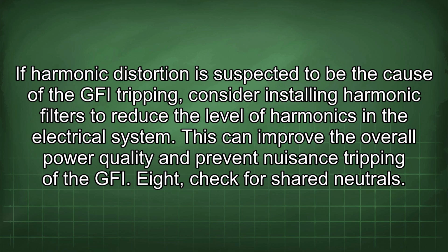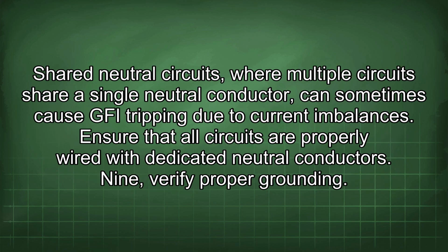8. Check for shared neutrals. Shared neutral circuits, where multiple circuits share a single neutral conductor, can sometimes cause GFI tripping due to current imbalances. Ensure that all circuits are properly wired with dedicated neutral conductors.